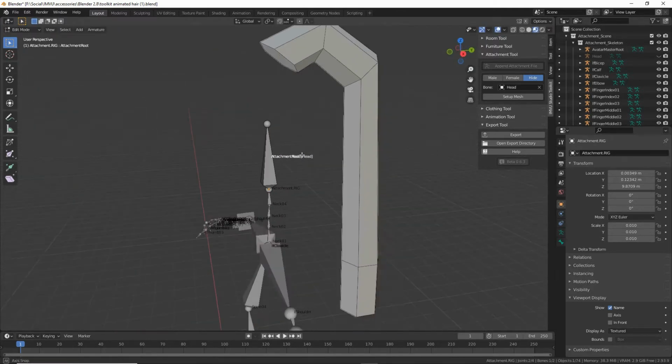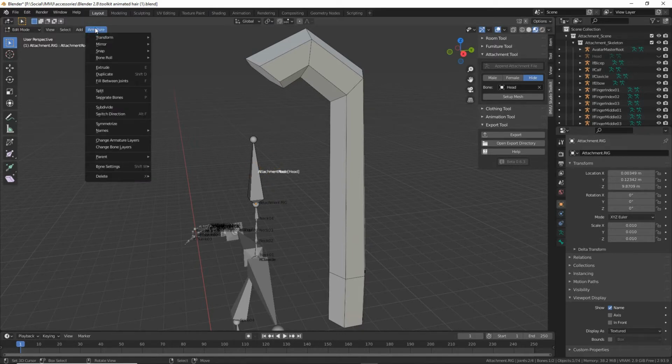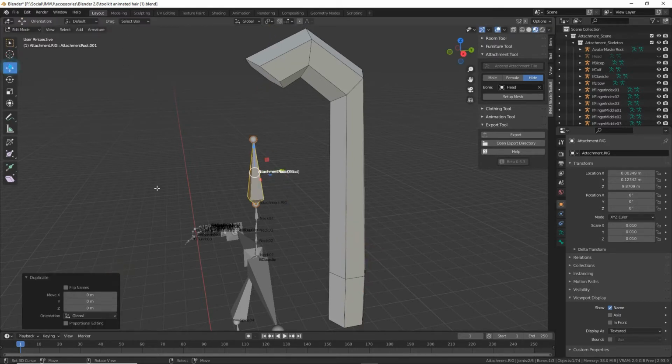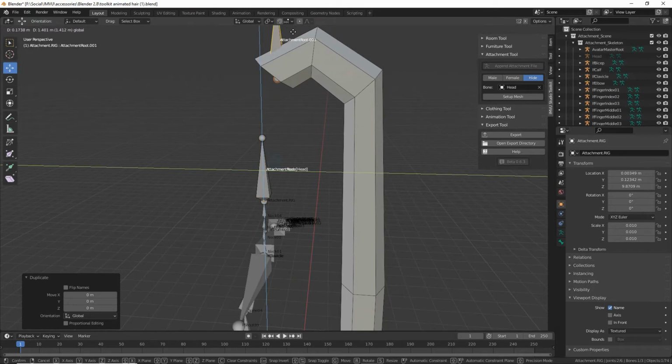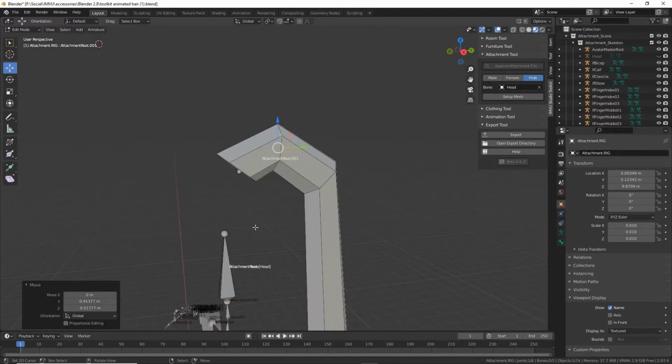This lets us into edit mode, where we can select the bones of our armature. So to make the rig, we can duplicate an existing bone. So we select a bone and just duplicate it. So armature, duplicate. That creates a copy of the bone. So press escape to release. Move it to the start of the ponytail using the move or transform widget. Then position the bone so it's inside the mesh.